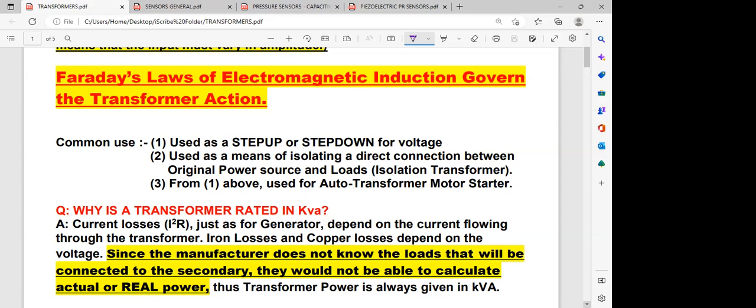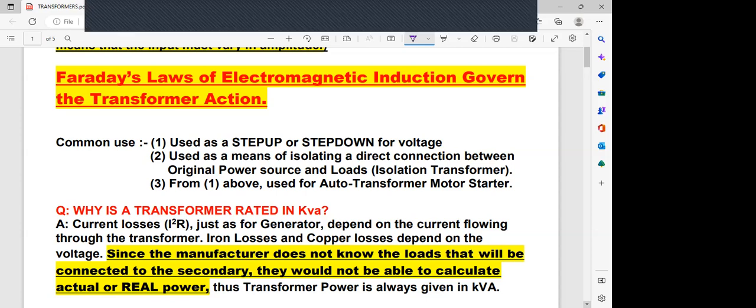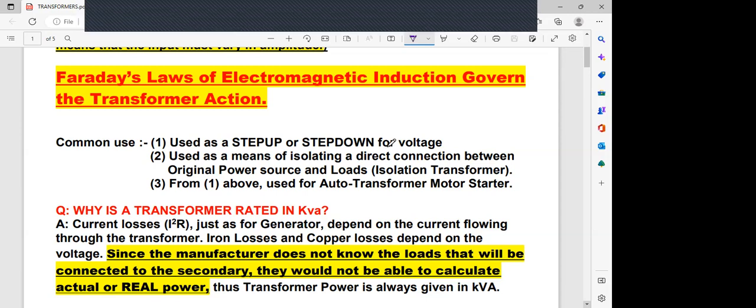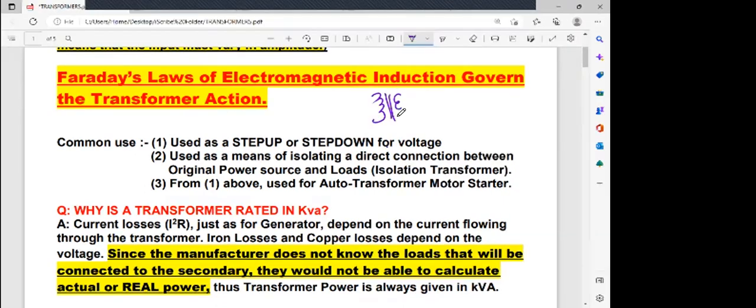Unless you change that electronic circuit, it is not going to go away. If you ask the company, the cost of that circuit is like buying a new washing machine, so they will say, try and do your best. They are not going to give you a new washing machine. So you do your best. You buy an isolation transformer where the number of turns in the primary is equal to the number of turns in your secondary.